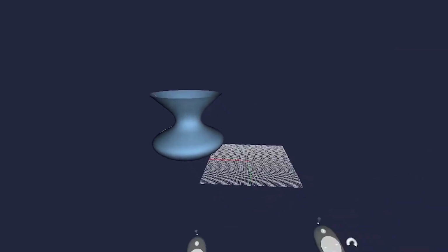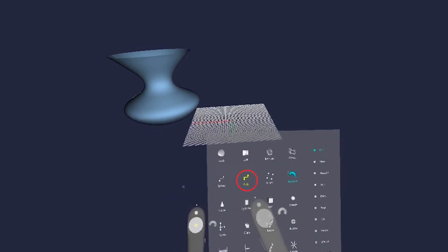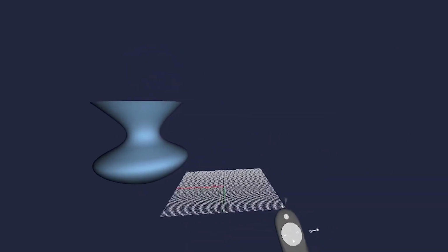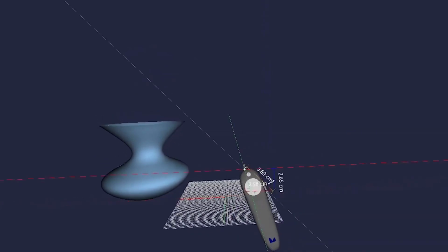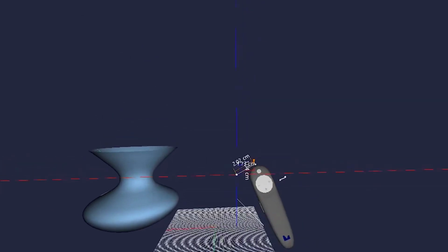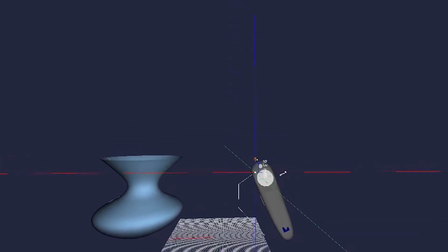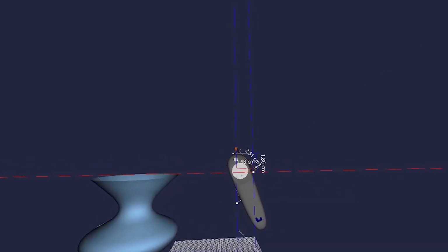Okay, now we're going to try a similar thing using a different command. The poly command allows you to create straight lines of which we can try revolving. So again, start clicking through a zigzag-like shape, trying to make sure to keep everything planar.